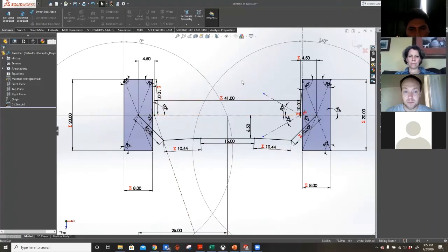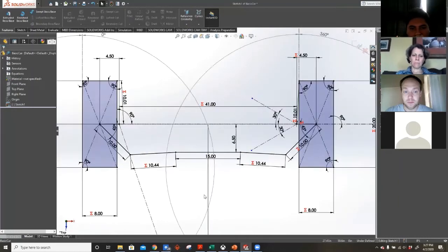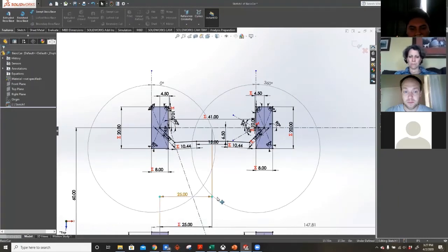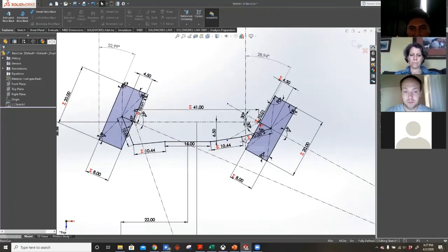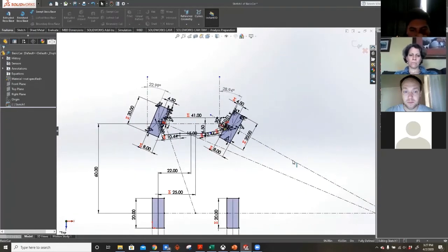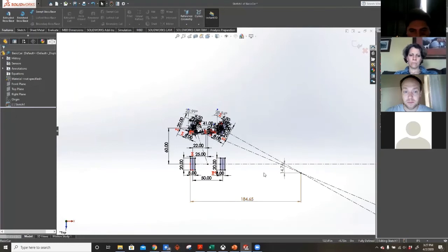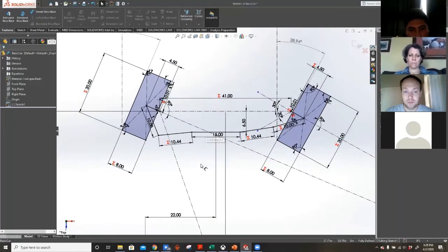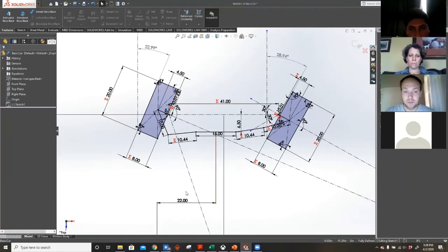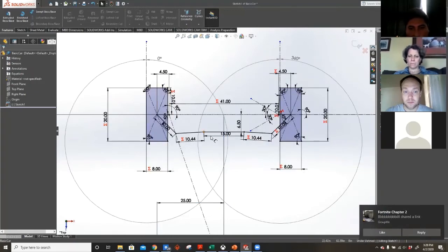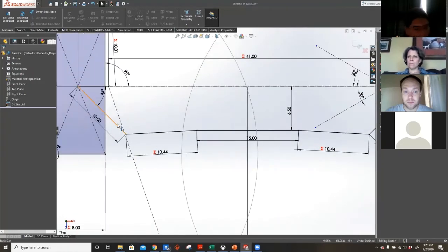So let's see what's your best you can do right now. Right now, with say 22, you're almost not going over center. But now we're looking at like 184 in terms of turning radius, and it's still pretty far back. The turning point is behind the axis. Well, you should at least go Ackerman excessive. That'll help your turning radius. So move it straight again, and then move this connecting point up and to the right. Maybe change it to 40 degrees.